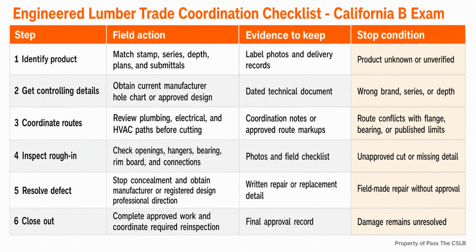Consider a hypothetical project where an installer trims the top flange of several I-joists to gain clearance for a rectangular return duct. The cut may look small compared with the joist depth, but the comparison is wrong. The removed material came from the flange where bending stress is concentrated. I stop the installation, support the affected area as directed by qualified personnel, keep the damage exposed, and obtain an approved repair or replacement decision. I do not let a schedule meeting convert that defect into an acceptable shortcut.